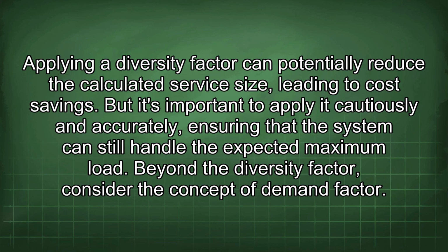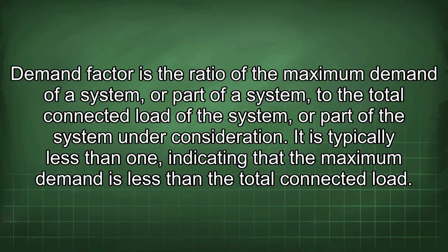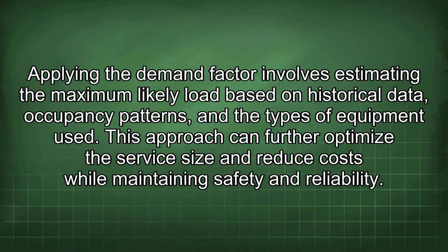Beyond the diversity factor, consider the concept of demand factor. Demand factor is the ratio of the maximum demand of a system, or part of a system, to the total connected load of the system, or part of the system under consideration. It is typically less than 1, indicating that the maximum demand is less than the total connected load. Applying the demand factor involves estimating the maximum likely load based on historical data, occupancy patterns, and the types of equipment used. This approach can further optimize the service size and reduce costs while maintaining safety and reliability.